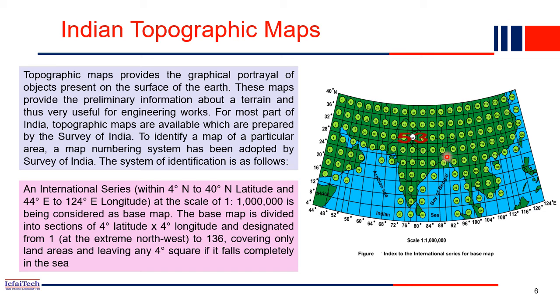Then we go inside each triangle, and subdivide it again into small triangles. From each smallest triangle we take the measurements: where the statue is, where the road is, where the park is, and what the distance is from the control point. We take all the measurements on paper in the field, then we come to the office, and by looking at these measurements we prepare the entire map of the region.